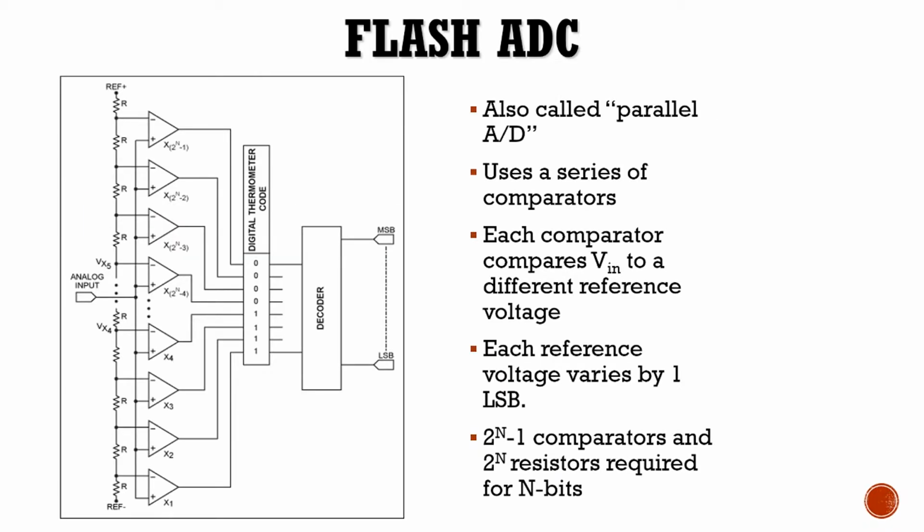Now, next is the flash ADC. This ADC and the other ADC architectures which we are going to discuss in a few minutes all capture the analog signal level at a single point in time every cycle, and if the input signal is noisy, these ADC techniques might convert a spike or a dip as they convert the signal repeatedly at a single point in time. This leads to the requirement of a sample and hold circuit, which was discussed earlier, to avoid this scenario.